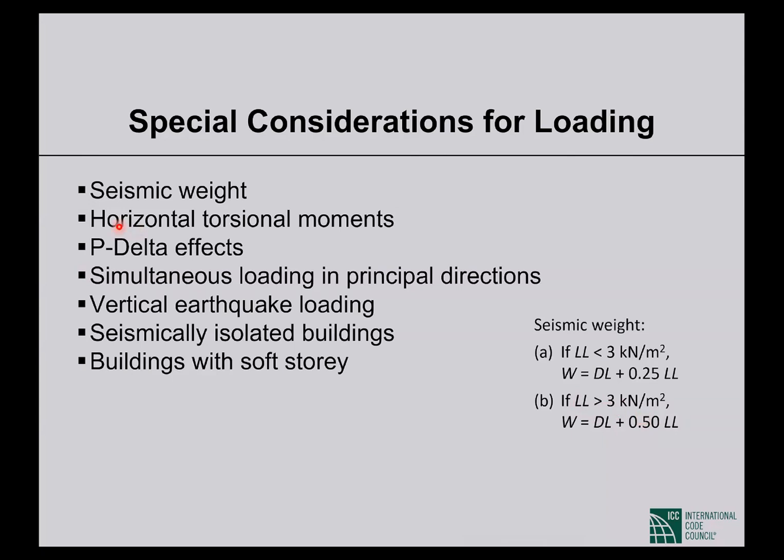Now, the other points, like if the building has horizontal torsional irregularity, or torsional moments, we have to calculate for lateral load. If there is torsion, we can calculate that. We have to calculate the average deformation of a story and the maximum lateral deformation of the story, and from those values we can calculate if there is torsional moment or not, that we need to consider.